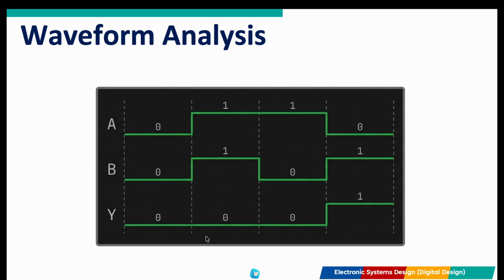We use this to verify critical timing relationships, ensuring signals meet setup and hold time relative to the system clock. We also check our control signals, like confirming that resets properly initialize the system and the clock pulses consistently. Finally, we validate the output logic, tracing signal changes across clock cycles to spot glitches or incorrect behavior before they become physical hardware bugs.